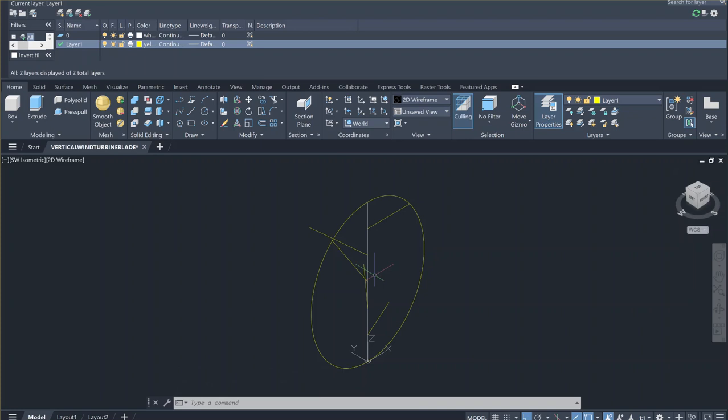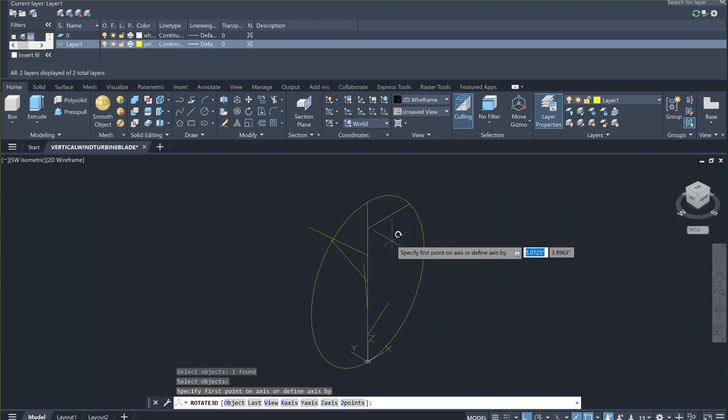And 100. So enter again. Rotate 3D command comes back. You select the line, end of the line, enter. Select the z-axis option, then select the end of the line. Now it's asking rotation angle 120 degrees, 120 degrees. Enter. So we are all done.